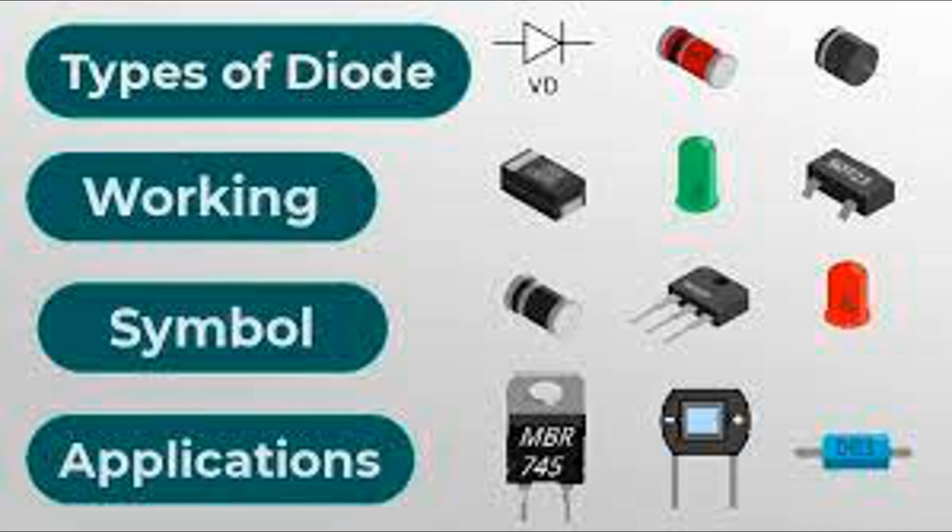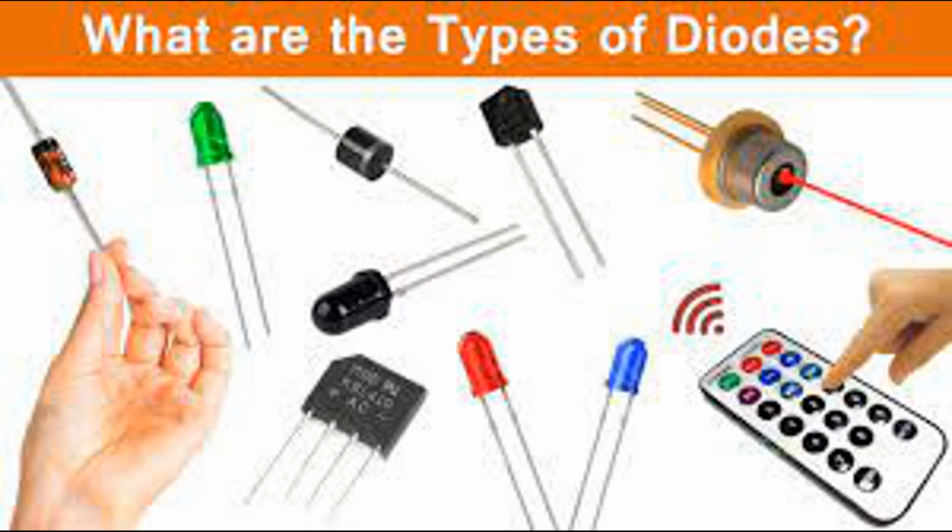Here's how rectification works. AC voltage input. The input to a rectification circuit is typically an AC voltage source, such as the output of a transformer or the mains electricity supply. Diode bridge rectifier. In most rectifier circuits, a diode bridge rectifier is used. It consists of 4 diodes arranged in a bridge configuration, which allows the conversion of both halves of the AC waveform into DC.